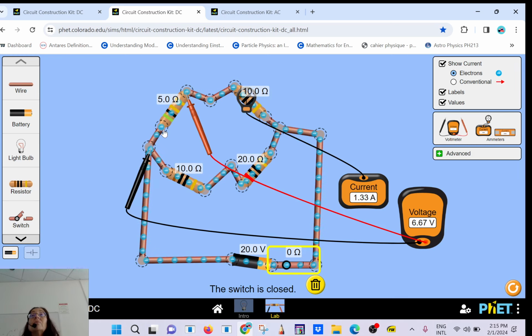So if you plug that oscilloscope, for example, into the outlet, you're going to see that here. What's going to be the peak voltage again? 170 volt. What's going to be the period? 0.02 second. What's going to be the RMS, which I measure with a voltmeter? It's going to be 120 volt. Is that clear? That's how it works.